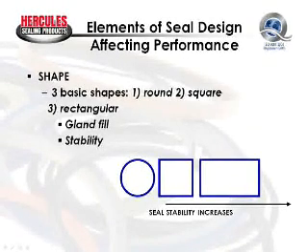So when you're designing a cylinder, you can pick the seal that you want for a particular application. You design the groove for that seal. However, when you're in a repair application, you must pick a seal which will fit the groove that you have. You always want to pick a seal that has the appropriate amount of gland fill to maximize the stability of the seal.